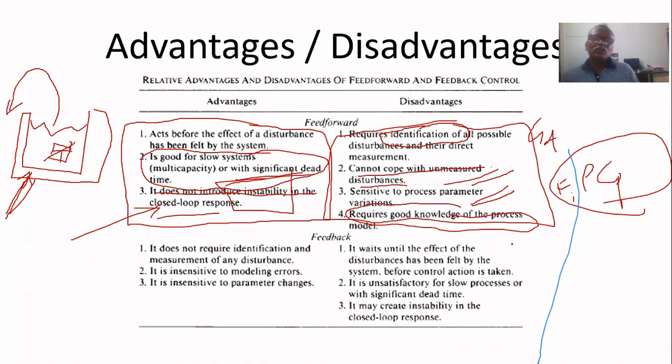But for an instrumentation engineer, if you give the mathematical model, he will design; no need to know the process. And of course, for the safety aspect, we must know something about the process, otherwise we cannot be a safety engineer. But to design a feed-forward controller, we need very good knowledge about the process. Then only it is possible to design the controller.